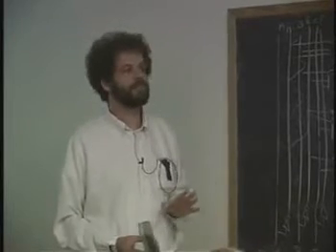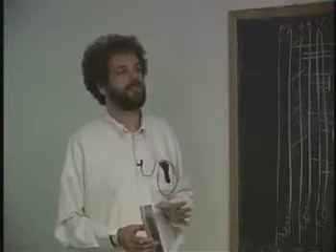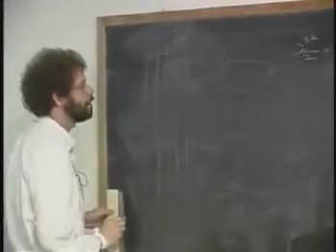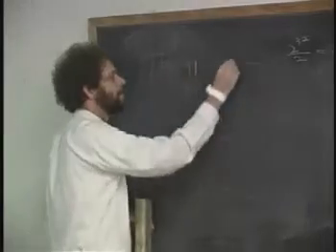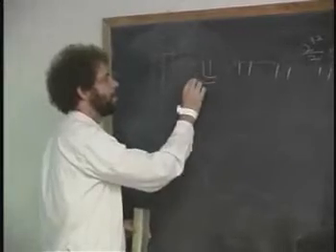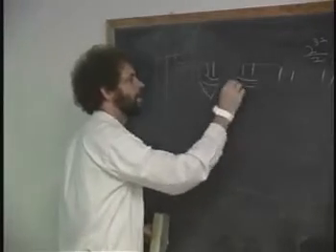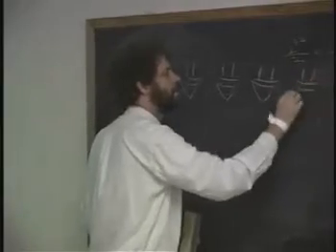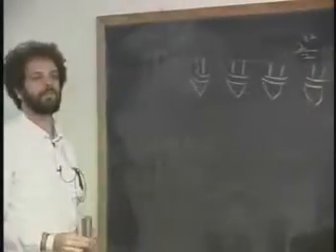So what's a better thing that you could do? Use XOR gates. Because XOR gates sort of have an intrinsic ability to do parity to begin with, and if I have a desire to do parity of n bits, what I'm going to do, let's say I want to do a parity function of 8 bits. I take a set of XOR gates like this, each of them with only 2 inputs. And now what do you think I should do with them?